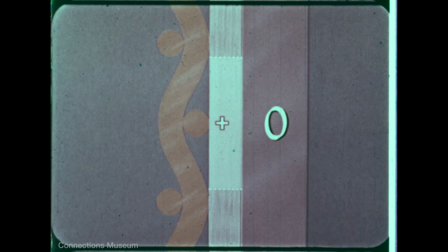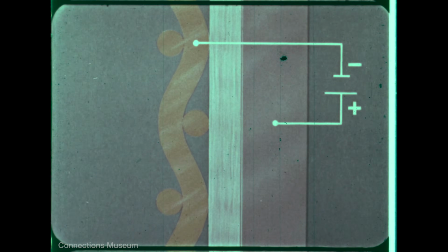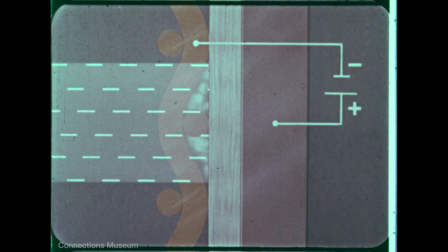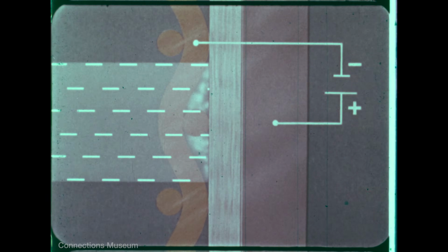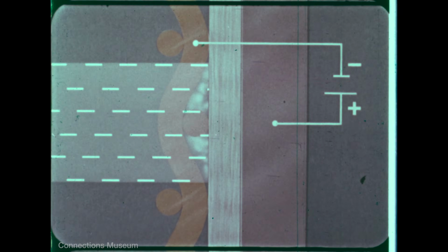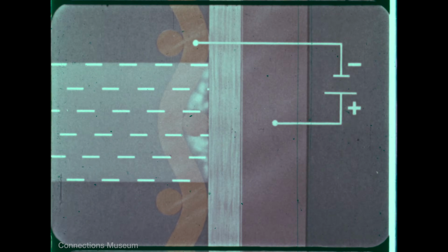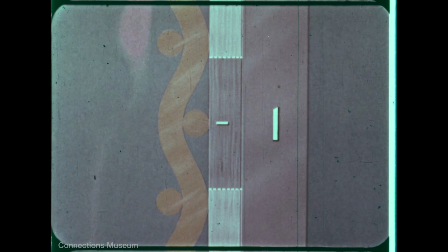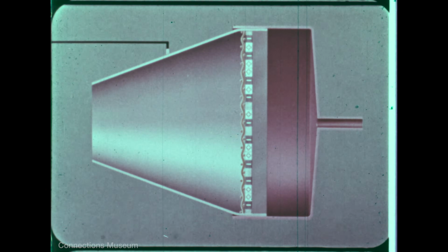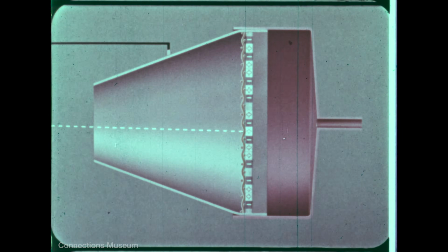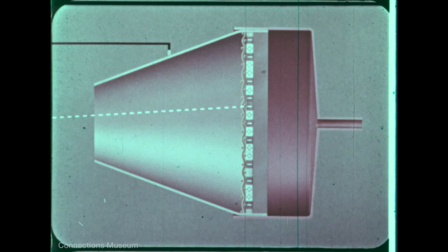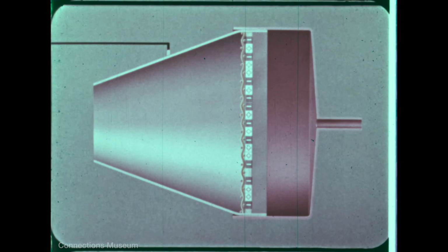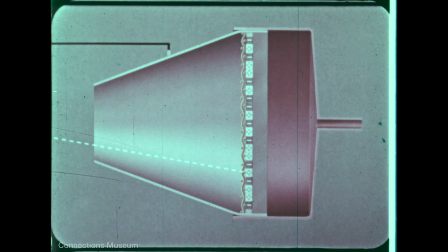When the beam and backplate potential are removed, the charge remains on the spot representing a binary 0. If a positive potential is applied to the backplate, the grid becomes negative with respect to the mica and will repel many of the dislodged electrons back to the spot on the mica. These, with the electrons arriving via the beam, will build up a negative charge on the spot, which when the beam and potential are removed will remain, representing a binary 1. The beam can be directed quickly to any spot on the mica at random, thus storing a pattern of negative and positive electrostatic charges representing 1 and 0 bits.